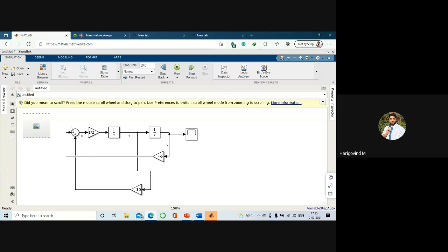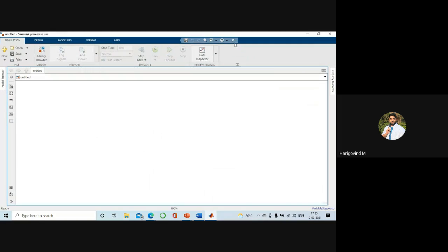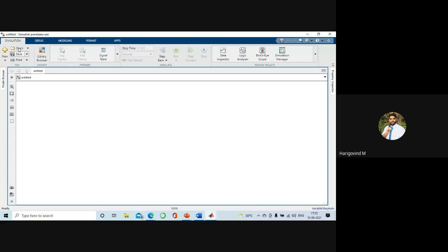The equation, I'm again saying, is a is equal to 1 by m times minus kx minus cv. I have given plus only, I have not given minus. Here you have 10, it is not minus 10, neither is it minus 400. So I have to change the sign here. If you double click the sum block in Simulink, you can open it.